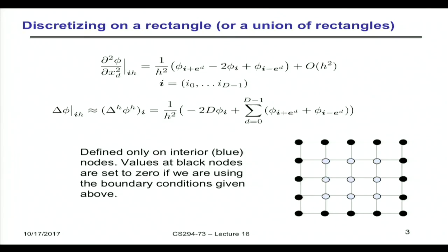Because we're only defining these on the interior values, we need to specify a value on the boundary, and that would be, for example, a Dirichlet boundary condition where we're saying the solution has to be 0 there. And then we can calculate everything in the interior pretty much with the information we have, and we're able to actually do this calculation. Now the problem is, this is a very small domain. You're not going to get very good resolution here. We want to do this on the order of 10,000, 100,000 in each direction here, so we can end up with a billion unknowns in a 3D problem very easily. And that's why we're looking at this for supercomputers.